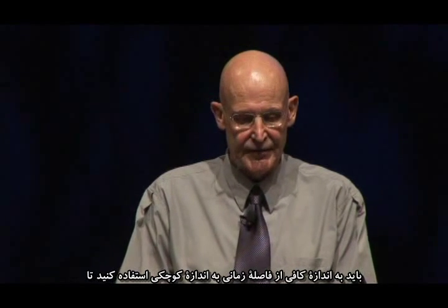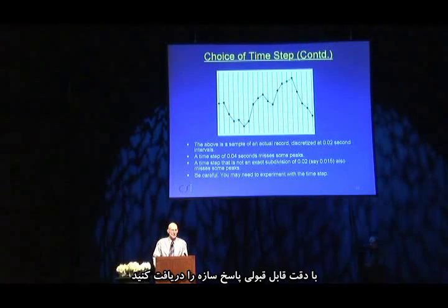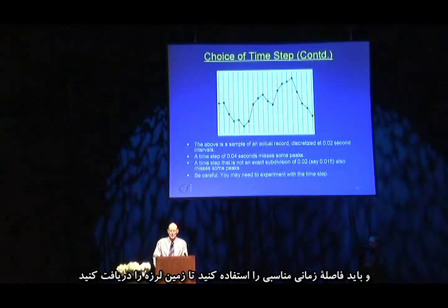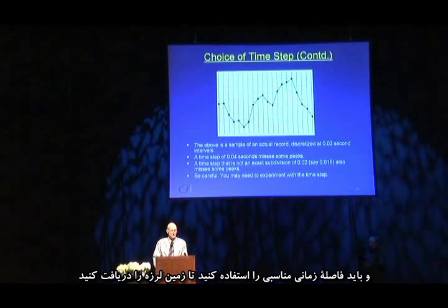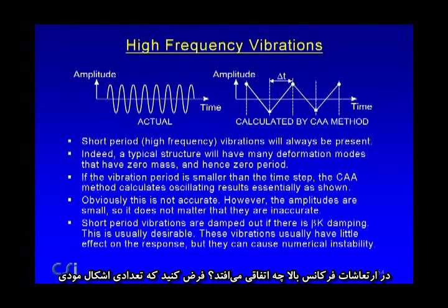You have to do two things. You have to use a small enough time step to capture the response of the structure reasonably accurately, and you have to use an appropriate time step to capture the ground motion. What happens with high-frequency vibrations?